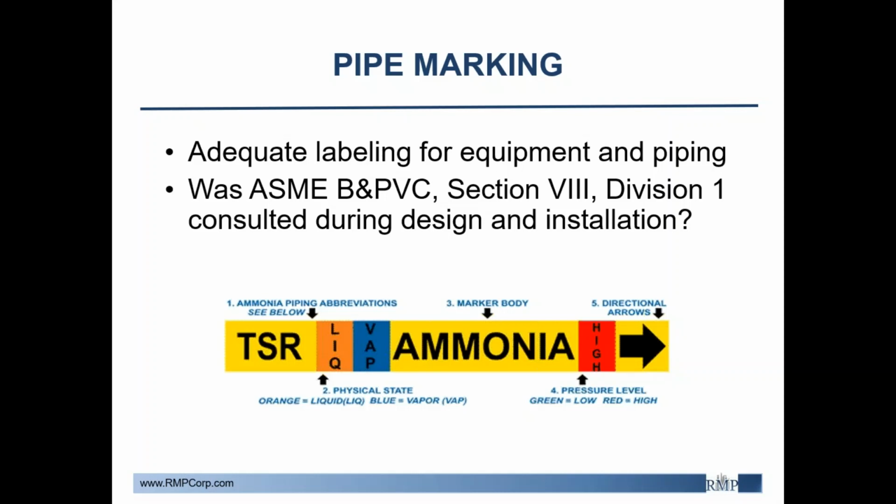But also what's important is looking at the ASME boiler and pressure vessel code, making sure that the design and installation meets those requirements. Again, a lot of this is already done in facilities, especially newer ones, but for those older facilities, or perhaps if it's never been checked, to verify that all this is being met.